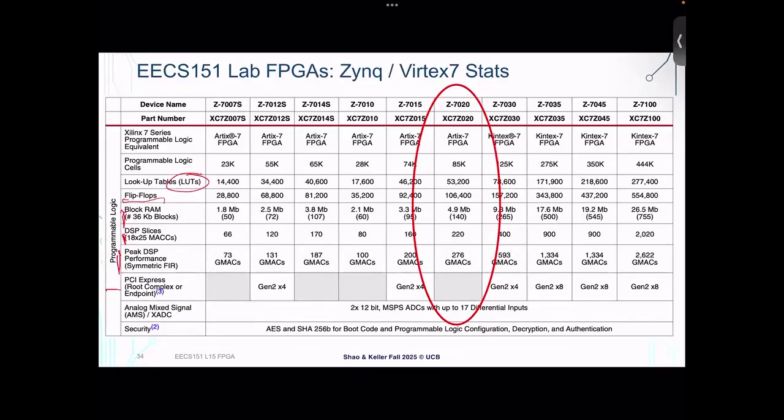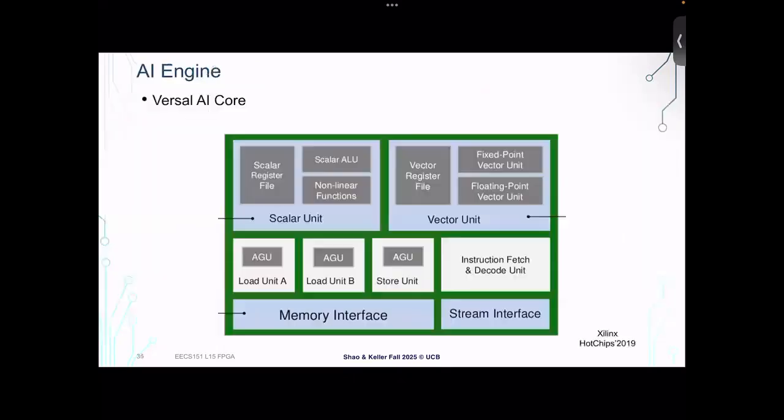There's a few other things that we haven't talked about. Notably, your Zynq parts are really nice because they actually have embedded ARM cores built into them. I don't think that you're using them in the labs at all, but it's very handy in the field to have a processor already ready to go rather than having to map it out of LUTs. And then there's some other bells and whistles as well. So about 5 years ago, let me just discuss this and then I'll take your question.